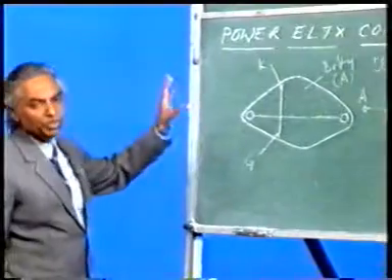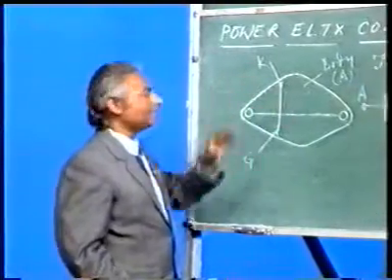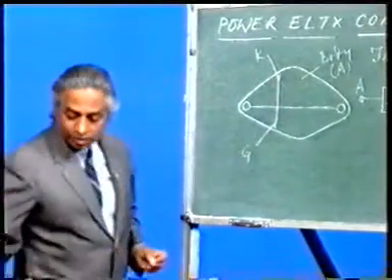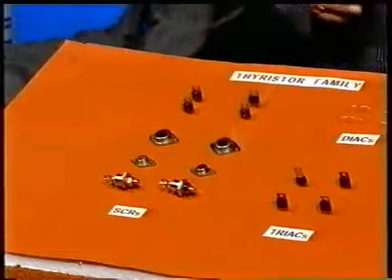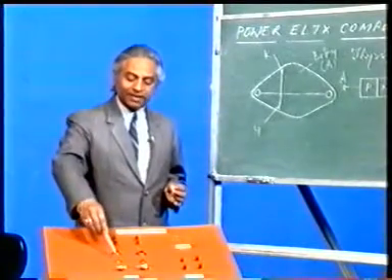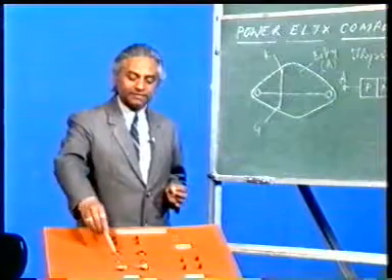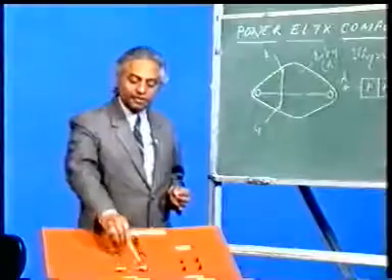So this is a universal method of finding out the terminals of a metal pack SCR. Similarly, you have these SCRs also, the same type, and you can find out the terminals in the same manner, but it is definitely of lower rating. This is of higher rating, this is of lower rating.